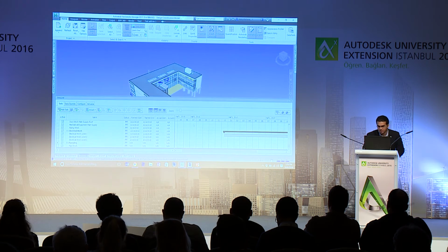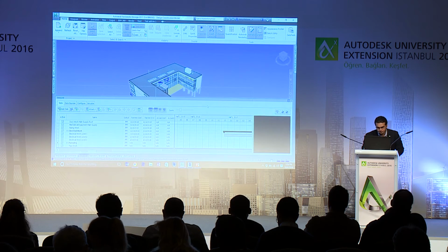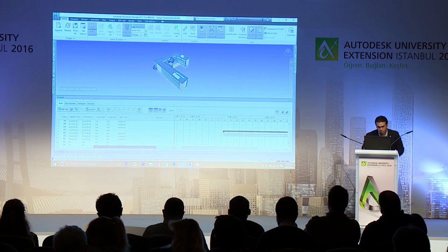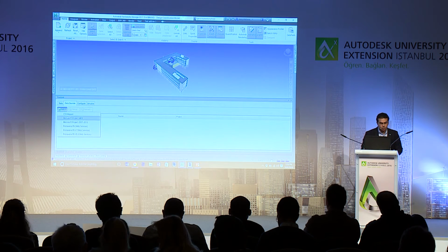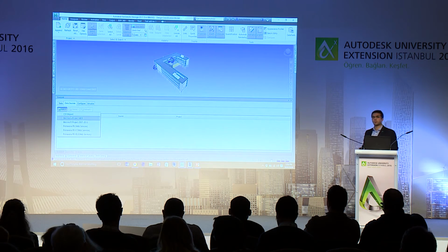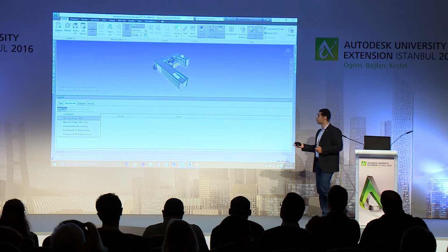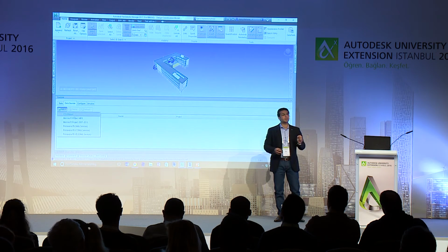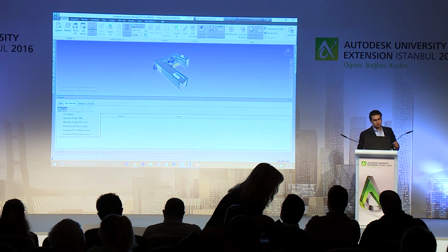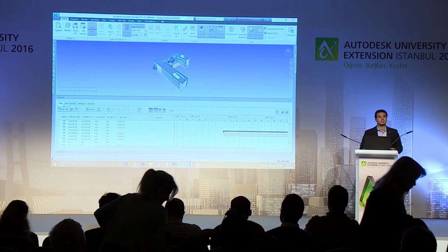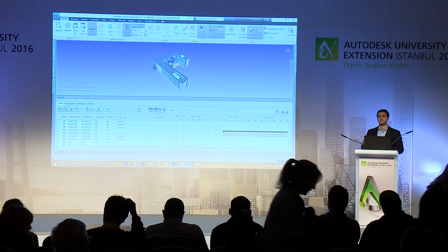Navisworks here, through the Timeliner, integrates with multiple planning applications. This includes MS Project or Primavera P6 if you want, or even a simple CSV Excel file. By importing your project schedule here, planners can visualize how their project will be executed.